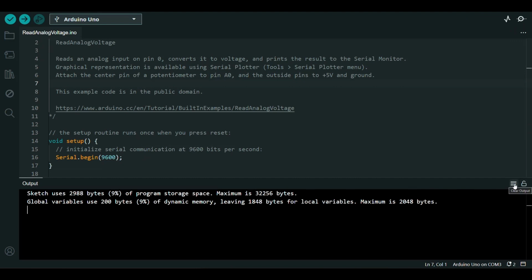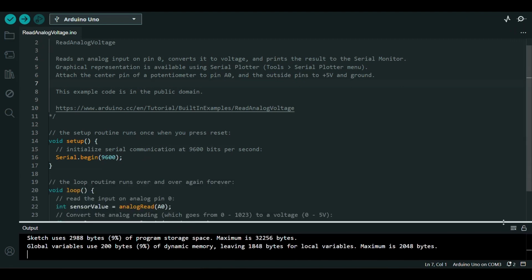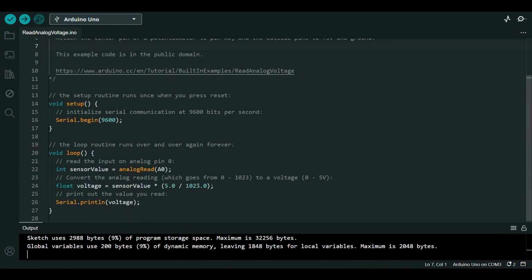When the shaft is turned all the way in the opposite direction, there are 5 volts going to the pin, and the input value is 1023. In between, analogRead returns a number between 0 and 1023 that is proportional to the amount of voltage being applied